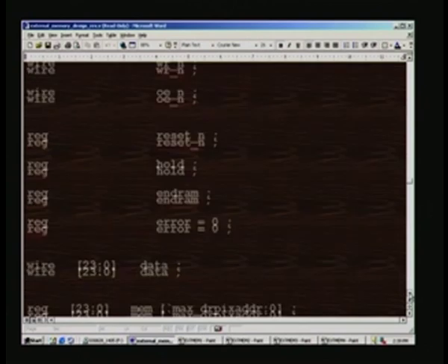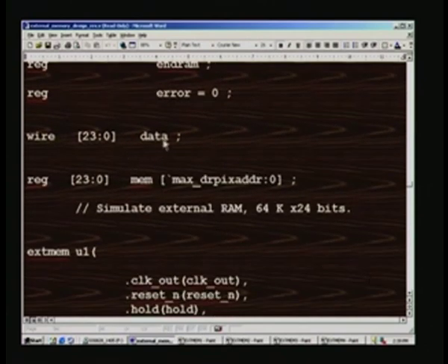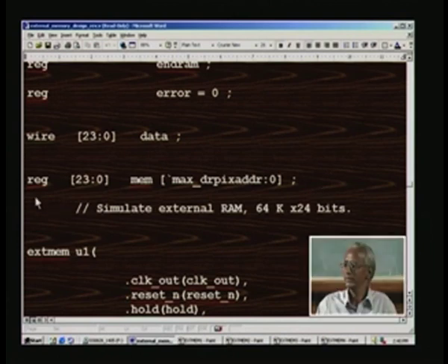being a test bench. Inputs must be reg, that is what we have here. In addition to this, we also have one data, and this is the test data that we have input in the test bench, and in this case it was all 5s, and this is the special instruction that you are already familiar with. What we are doing in this test bench is simulating an external RAM right in the test bench.